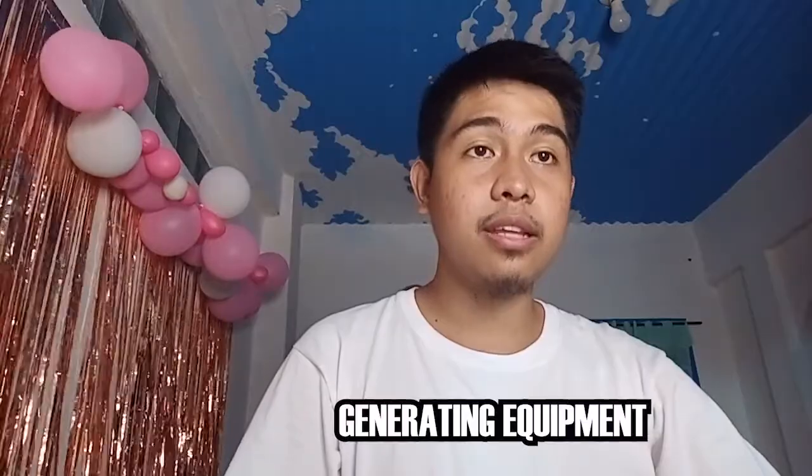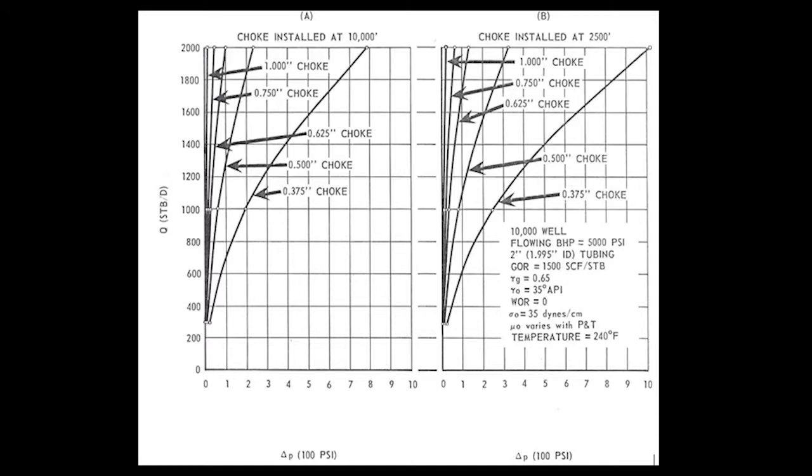The subsurface choke is the second significant source of possible pressure reduction within the producing equipment circuit. Within the tubing string, subsurface chokes are inserted at varying depths. The choke's installation depth is mostly determined by the service function it performs. Based on the picture, it shows the pressure drop effect for 5 different choke diameters at varying flow rates.